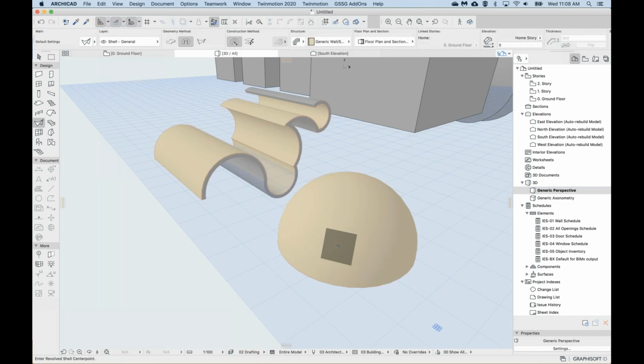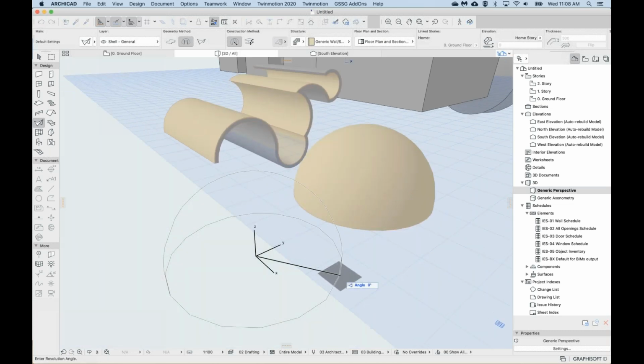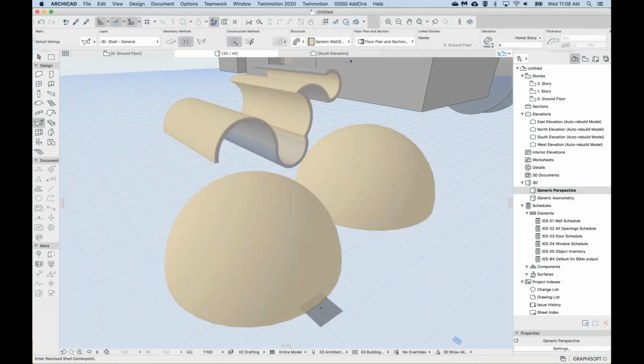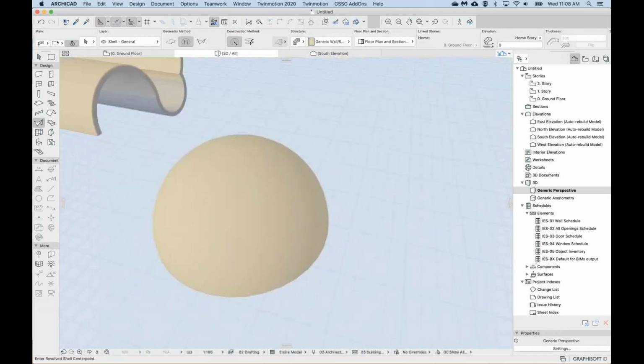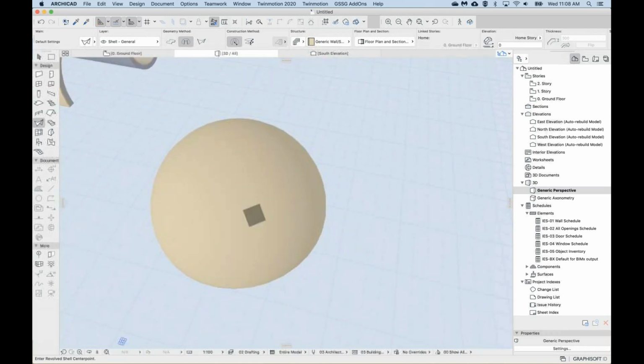So what I find easiest is do center point and then double click, so radius, and then click again, and this will do 360. So shell, revolved, so the second one, and the simple. So we just need center points, radius, but then do a second click on the radius. And we should get a dome.